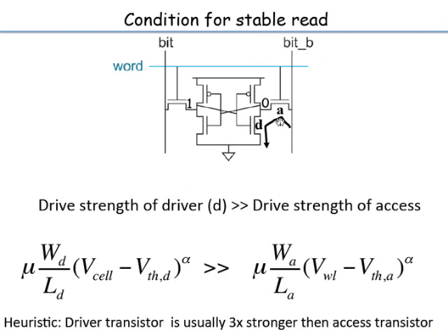But what happens is that if you increase the threshold voltage of the access device, the current you can pull from the bit line is determined by the current through the access device. So the current, what is called I cell, the cell current, the read current becomes small. So it takes longer for you to do the read. So you take a hit in the read time. We'll also see when we study the writes in the next lecture, you don't want to make this access device too weak, too feeble, because then you can't do a proper write.